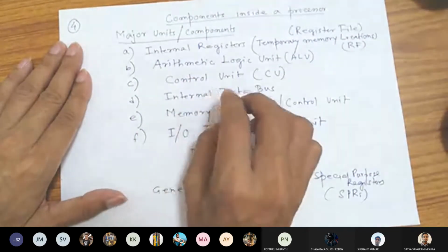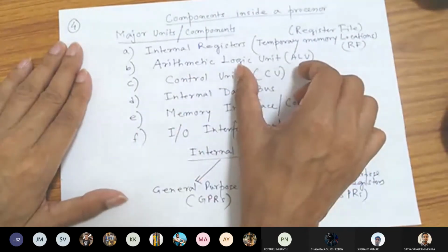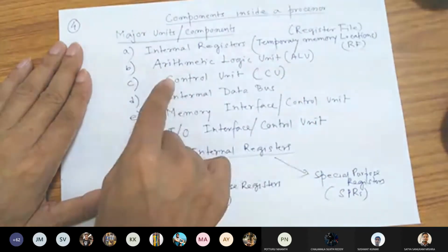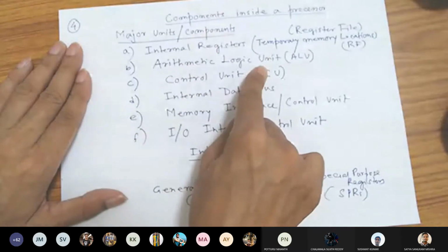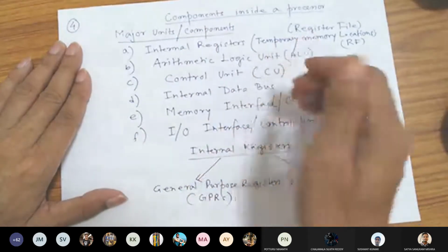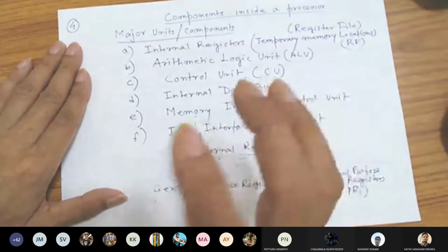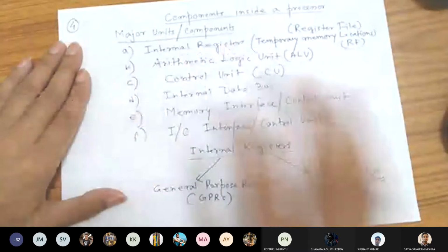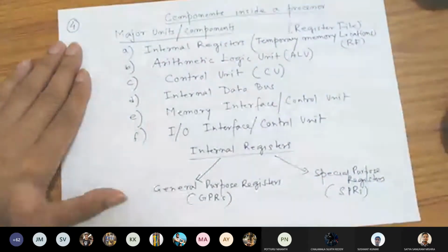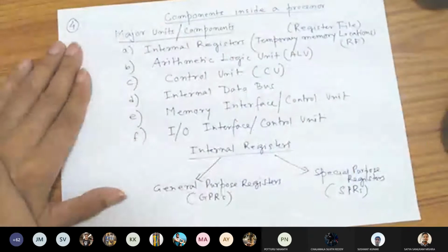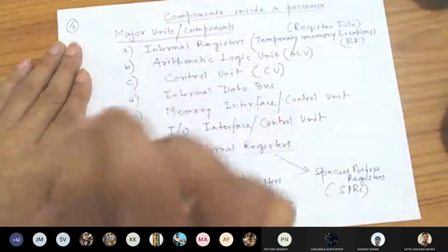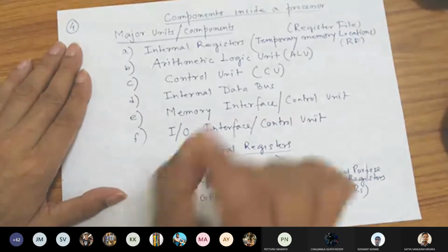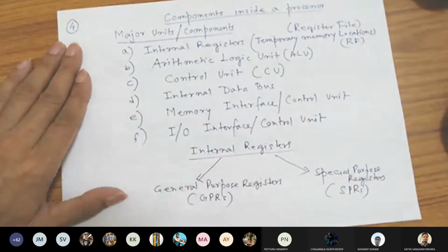Now I am not explicitly mentioning what the size of the control unit will be. The input to the control unit can be X bits, because the program initially goes to the control unit and then the control unit performs the operation. The output of the control unit may not be 8 bits always. It may be more or less than 8 bits, depending on how many signals are required. The control unit generates all the control signals, so we may not be able to specify how many control signals will come out of it.